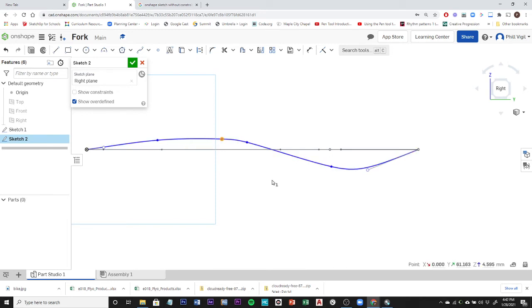How about that? So this is just a line, has 0 thickness. We need this to be a region that we can extrude. So we need to somehow either trace the outline, or you could use the offset tool, which would make that process a little bit easier. Those are two different ways to get the same result. The offset tool is going to give a specific distance away. So that's this tool here.